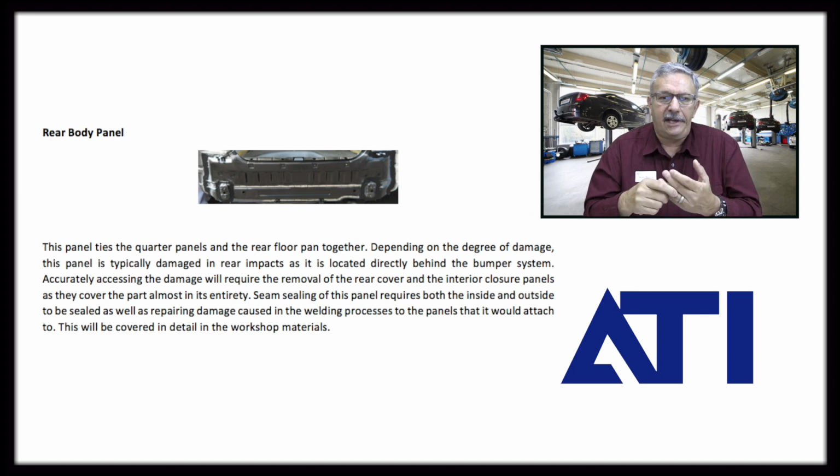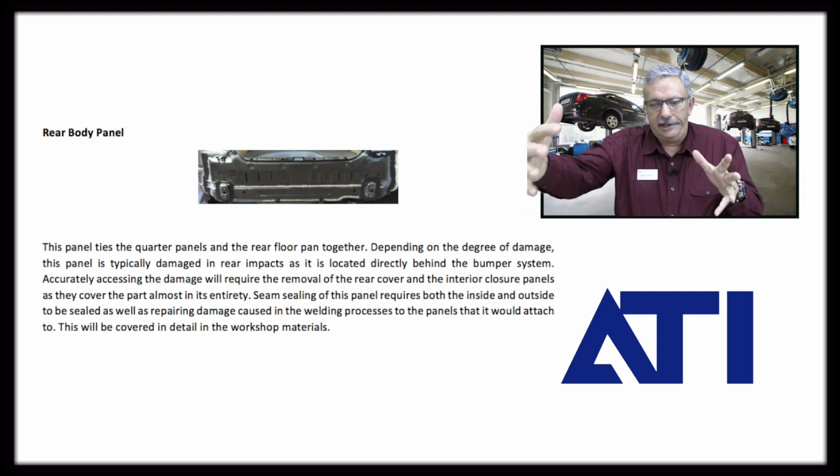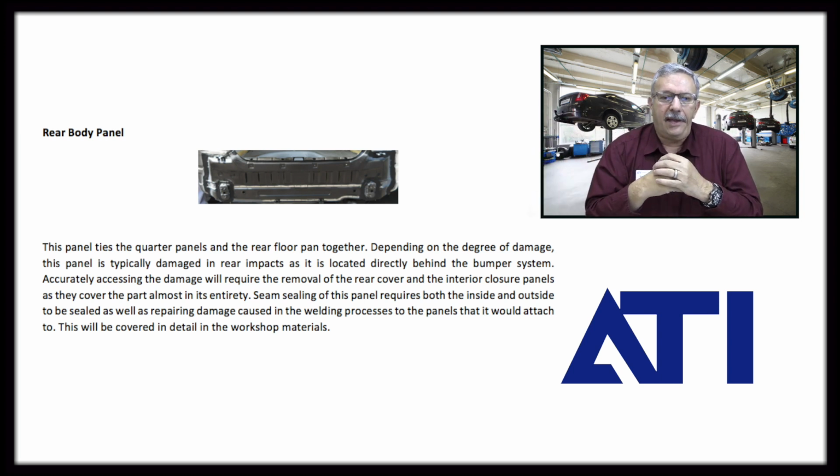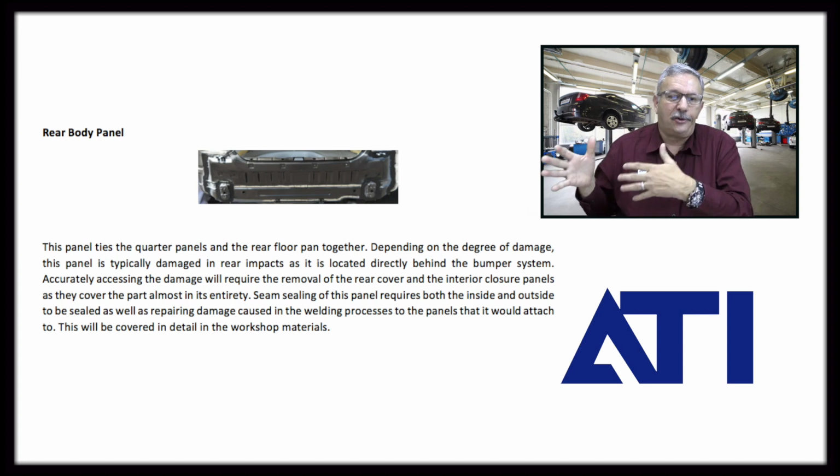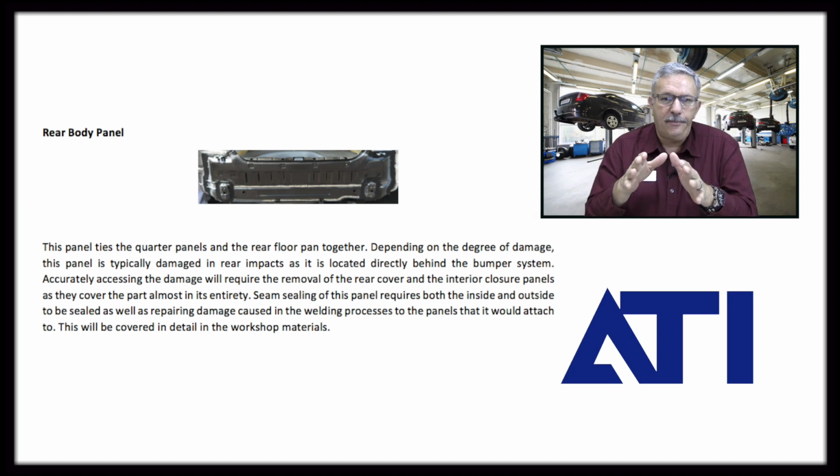About 47% of the accidents that we see, the left front of the vehicle is involved. About almost the same number, it's the right rear of the vehicle that we see involved. So this rear body panel is something that we see damaged quite often. And it is a structural component in that it ties everything together and does attach to the frame rails. So we do see where the degree of damage will dictate whether this part can be repaired or not.